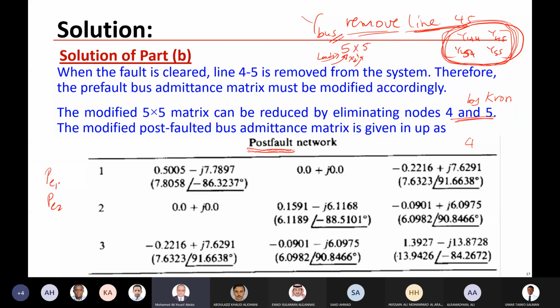We have to start with load flow, and then you calculate the currents, and then you calculate the E prime, and then you calculate the Y bus of the load flow, and you adjust it to include the loads and the reactance of the machines. And then by column reduction, you eliminate all load buses. You keep only the generator buses. And then you can calculate the E 1, 2, 3, whatever number, and you can write the swing equation.